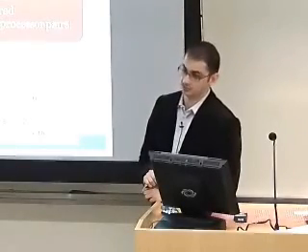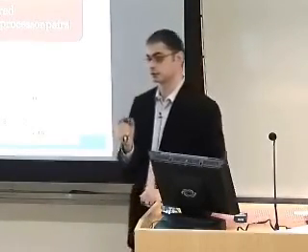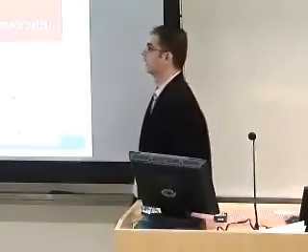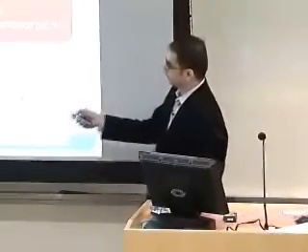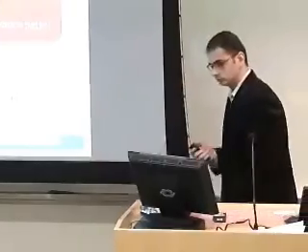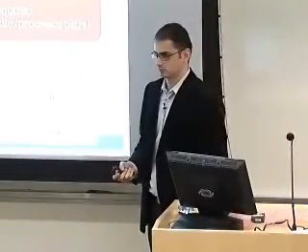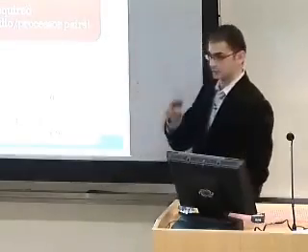It will affect it if you have a lot of data traffic, but you have to remember that the actual MAC mechanism of the 802.11 is a way faster and more efficient mechanism than the actual 15.4. And you will be able to see that right away. So right now, what I'm talking about is that we have to do this matching between the processor and the radio. And the second thing that comes up is that it's not just enough to compare the energy efficiency of the radios. The reason is that we have to pair these radios with specific processors. So instead of comparing radios, we have to compare the energy efficiency between processor-radio pairs.